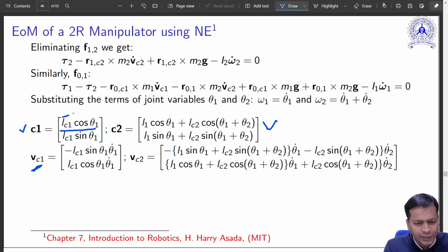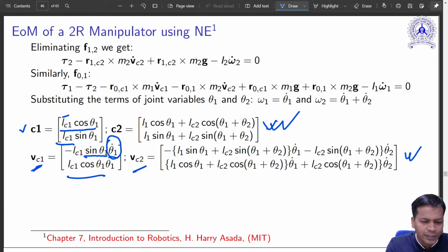This is a constant, so the derivative of cosine is sin A, theta 1, and then theta 1 itself is a variable. So you will get theta 1 dot. So what is that? This is the angular velocity of the first joint. Similarly, you did this, you got this, and taking the derivative of this, you can quickly obtain this. So these two are the velocities.